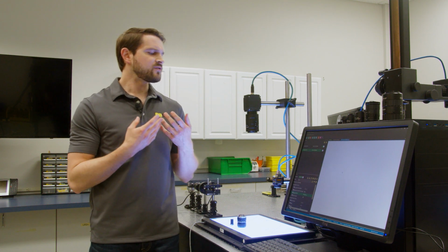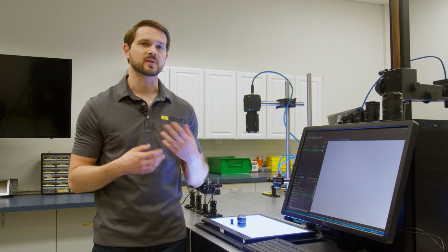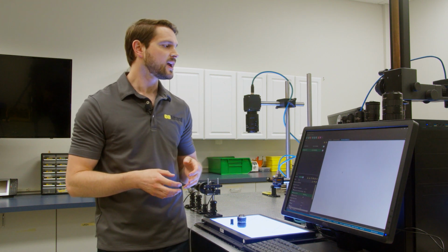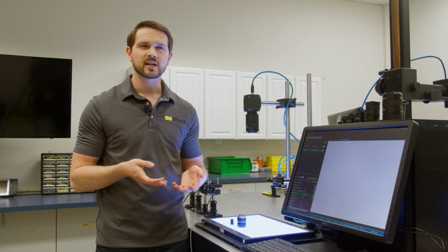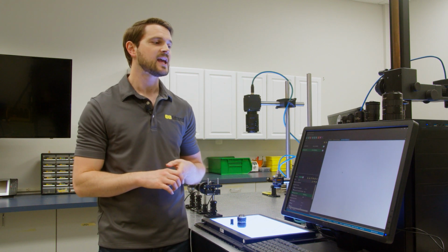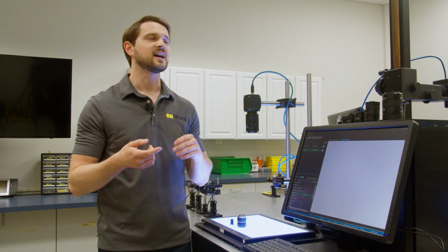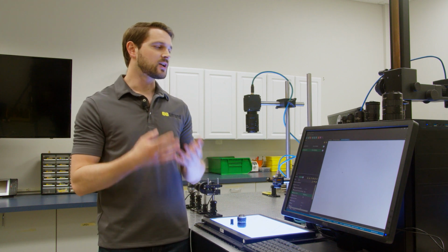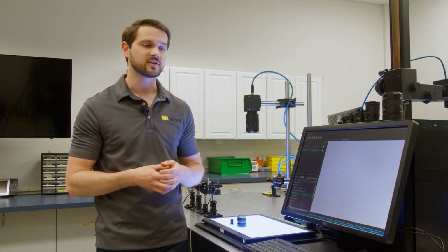If you're going to pair a lens with a particular camera, that's one of the first specifications you'll want to look at, aside of course from resolution and distortion specifications: can it actually cover my camera? That specification is generally notated as maximum sensor coverage or maximum sensor format, and the number used is usually some fraction of an inch. So you'll have 1/2 inch, 1/1.8 inch, or 2/3 inch. The list goes on. It can also be something like an APS-C format, which is what this camera is. So in some cases, they're not necessarily fractions of an inch.